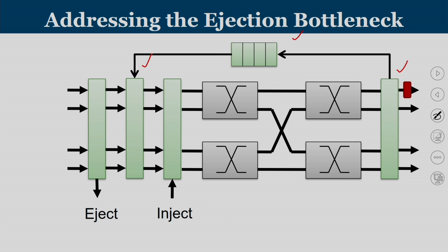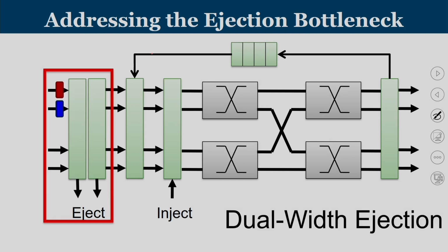So, this can be eliminated by a mechanism by which that particular flit can come and get ejected only in the subsequent cycles. So, it has to go around the network, come back to the same router and then get itself ejected out. Can you improve upon the scenario? And that is what we are going to see here.